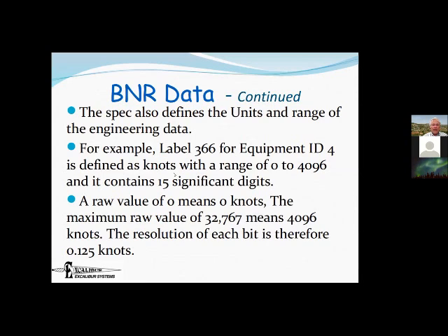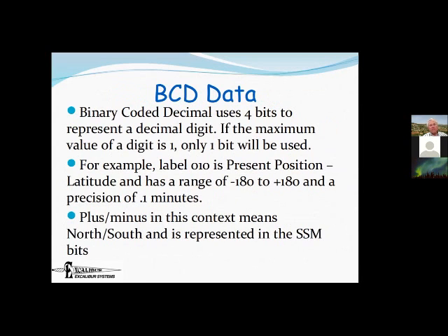So we've got in the spec the number of bits, the resolution, and the range, and they all have to fit together. Right? If I had said that I'm only giving you 12 bits with a range of 0 to 4096 and a resolution of 1/8, that would be impossible. So you have to check the spec, and I'll show you later. It's really important to check the spec because they sometimes lie a little bit.